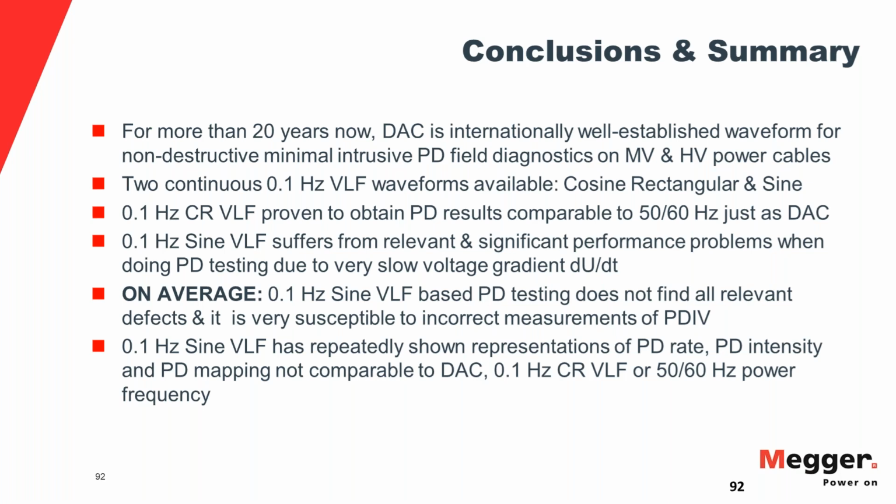And now one more last comment. So why would you ever use slope if damped AC seems to be the gold standard? Well, the latest, hottest thing in the industry is moving away from just VLF testing, going to monitored withstand testing, which means you do a fully compliant VLF test because you have to do this. It's your withstand test for the commissioning. But you record a diagnostics indicator, and that is for new cable installations, preferably the PD.